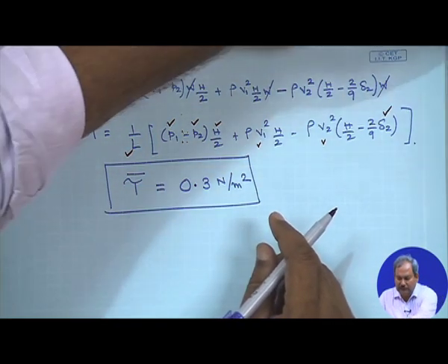So this is a good problem, an ideal problem to demonstrate the utility of the momentum integral equation even for solving the case of turbulent boundary layers. So this would really help in obtaining a quick solution, because as engineers you would be mostly interested in the value of the shear stress or the force.